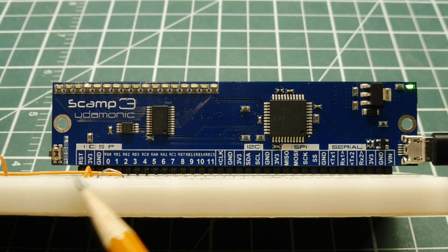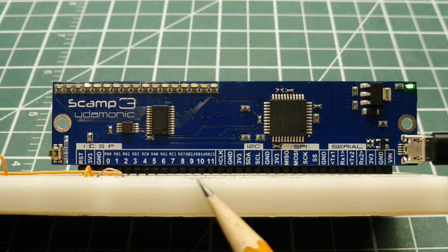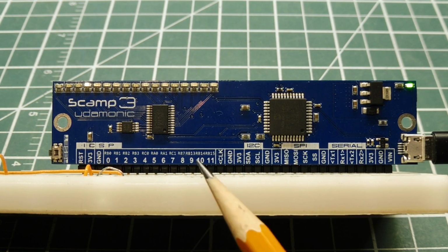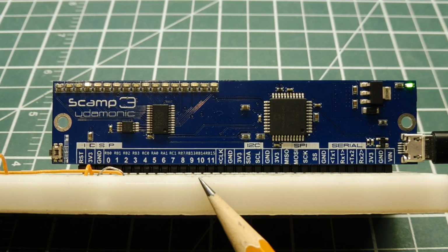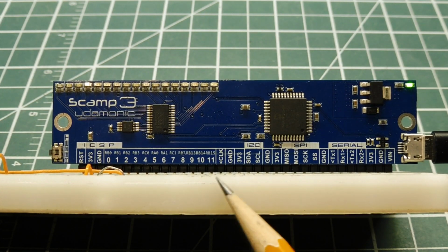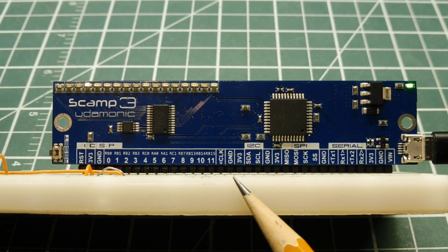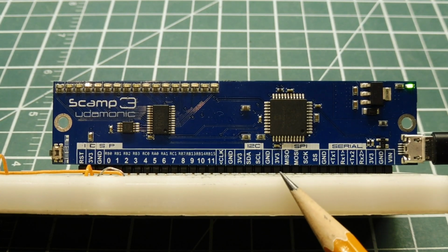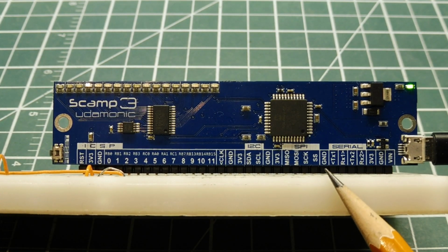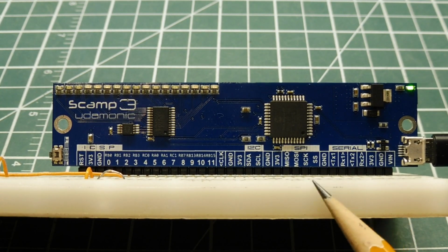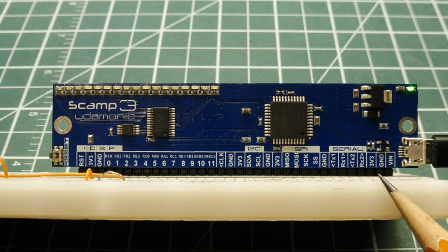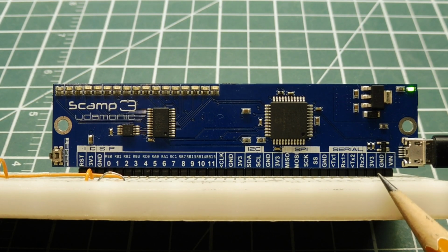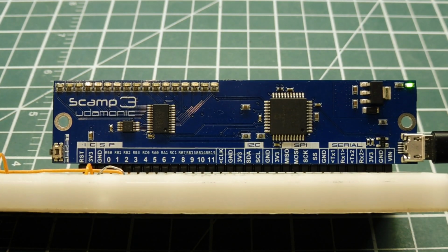And if you look at the very left, we can see a reset pin, and we have 3.3 volt output, and then we have 0 to 11 GPIO pins, so we have 12 GPIO outputs. We have a system clock that's 16 megahertz. Then we have the I2C bus, SDA and SCL. We have the SPI bus. Then we have the serial bus, that's UART1 and UART2, TX and RX, and they're hardwired to these pins. And then we have a VIN, so we could power this board from an external power supply. But in this video, we're going to look at PWM.